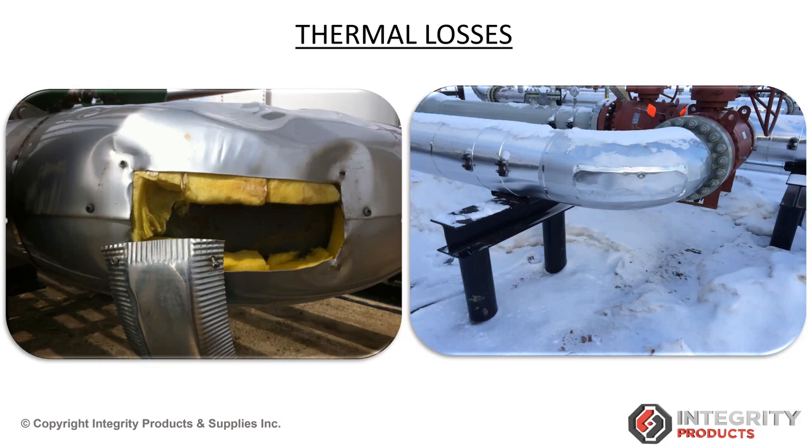Yeah, here is something: if we just try to take this system and compare it as per API 583, the very simple question that we can pose to ourselves is whether the risk rating for this system before making the window is the same as it is after making the window. Also, the other problem could be the risk rating for CUI. The other problem could be the thermal losses. Definitely, if a system is running at high temperature, we need more thermal energy and more fuel to maintain the same temperature of the system, and thermal loss is definitely a problem in that case.